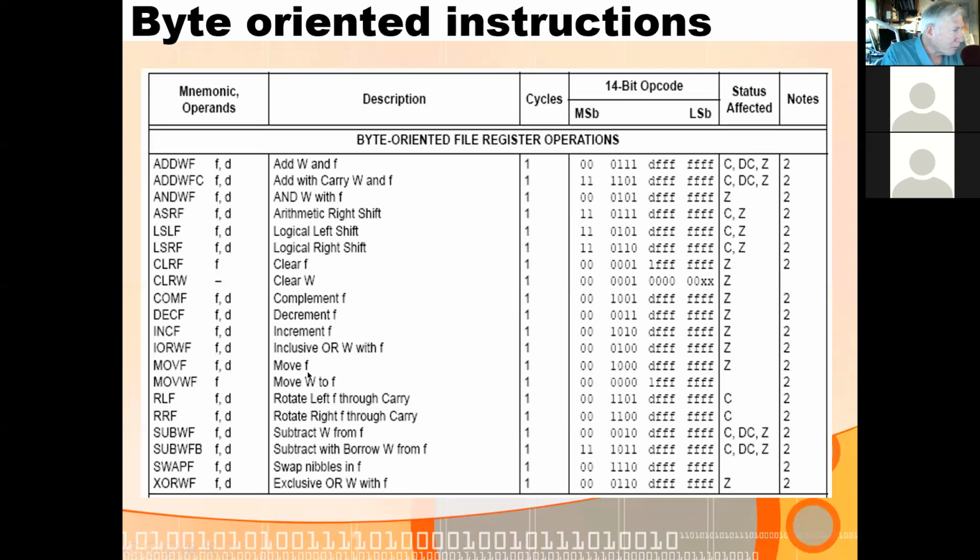Okay. So here you have an add. Here you have an add with carry. So it adds the contents of W, the contents of F, and the carry bit, whether it's set or cleared.